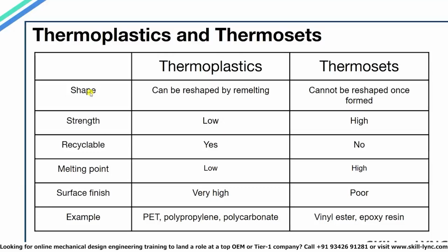This property of thermoplastic makes it easier to shape, and that is why for making plastic components using injection molding, we use thermoplastics. Most of the plastic components used for making a car, around 90%, are also thermoplastics. An example of thermoset would be your cooker handles. These handles are made from bakelite, which is a thermosetting plastic.